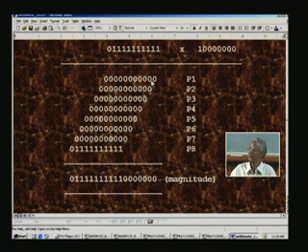What we have to do is for the rest of the number, we will take the entire thing, bifurcate it into LSB and MSB, and then add at every clock only the LSB, and then at the following clock we will add the MSB as we had done before in the adder case, and we will follow the very same pattern here, and at every stage it is going to be the same. The subsequent addition will have a result arising from this.